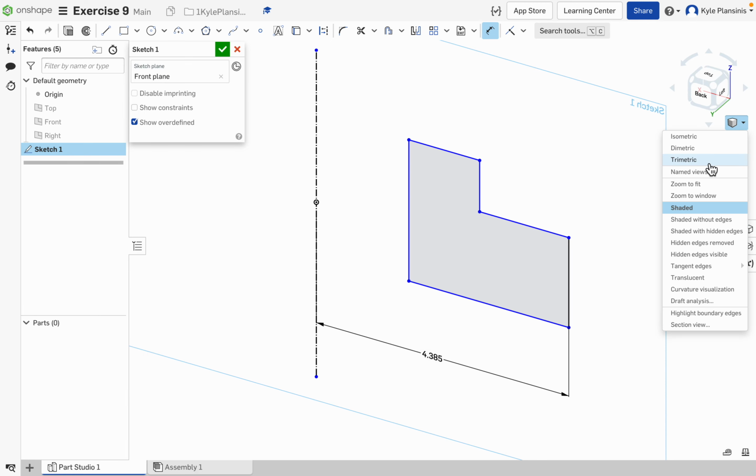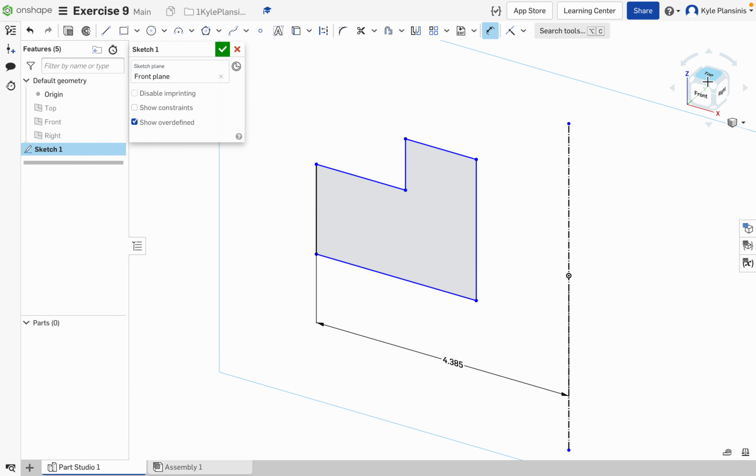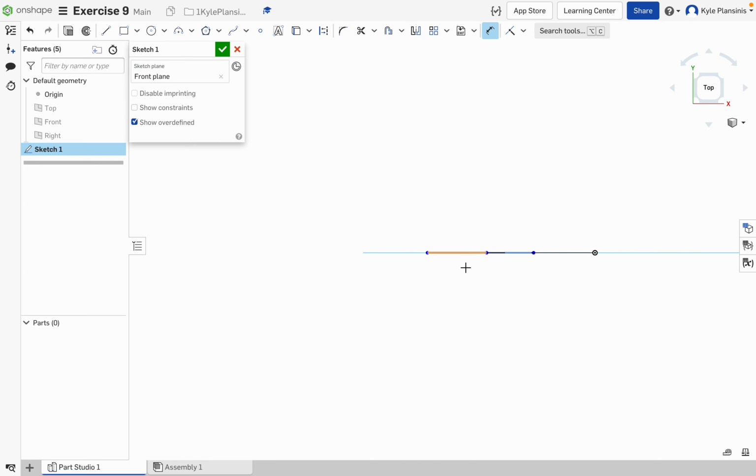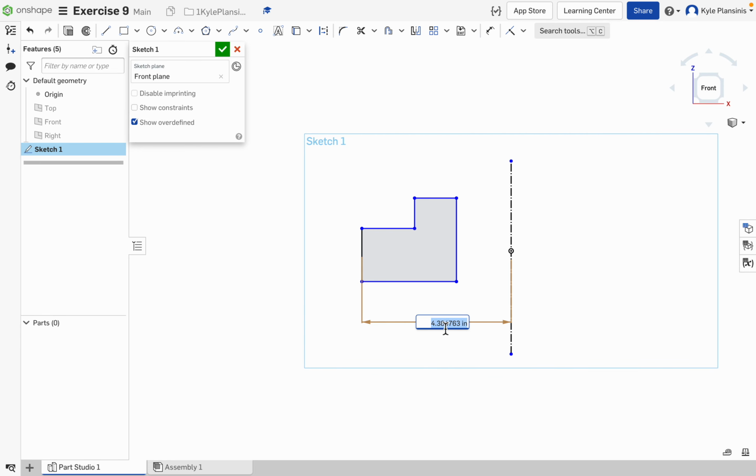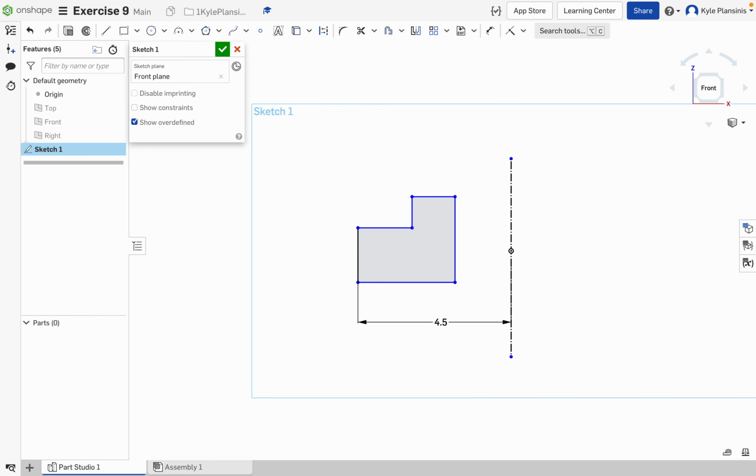So you have to think this is the furthest point out, and it might actually help if I go to the top view. So you can see here's my shape, and it's going to spin the entire way around, and right now I'm on that line here. So that's going to be the outermost point of my circle. So let's go back to our normal view here, and this dimension is going to be 9 inches, so it's the radius, which means it's cut in half. It's 4.5.